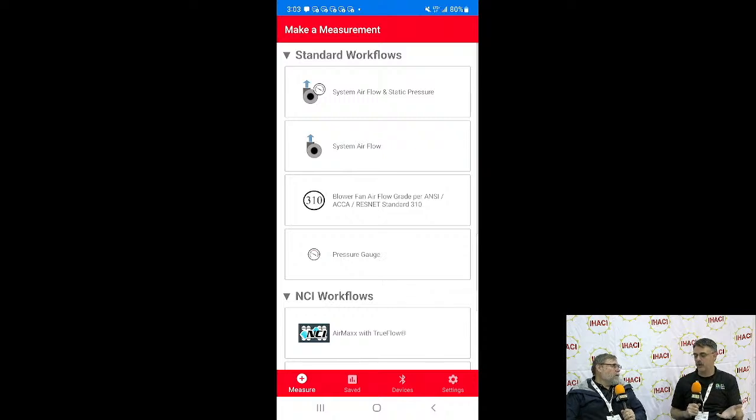Correct, because you know that going in on the head end, rather than putting in a new piece of equipment and then finding out it doesn't work. That makes you look bad. It makes your customer really question your credibility. And then you get to tell them up front, hey, not only do you need a new piece of equipment if you want to go with this, you also need to do some work on the duct system. Maybe it's just putting in a bigger filter.